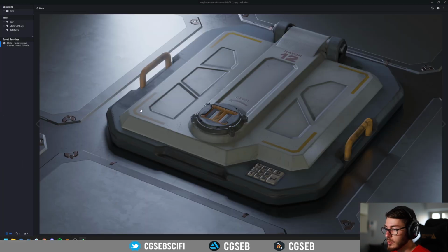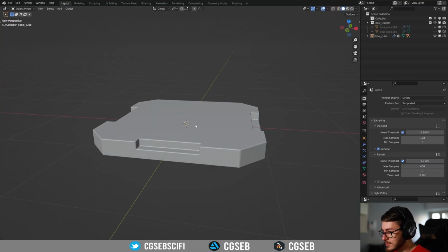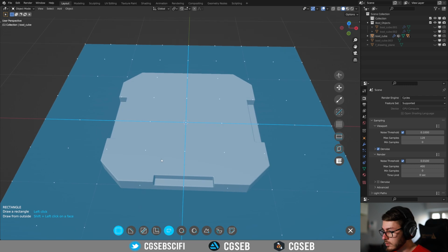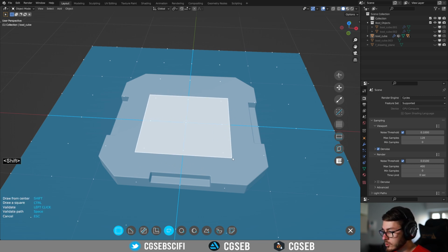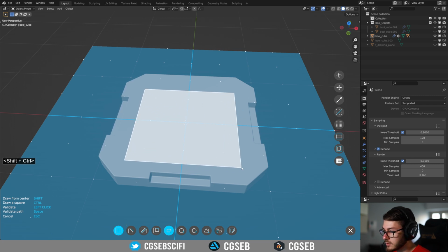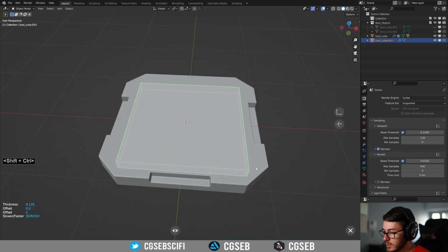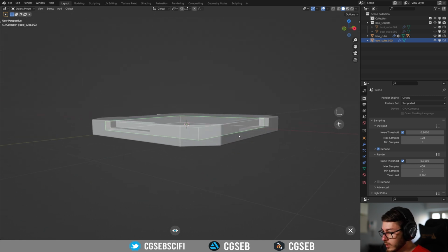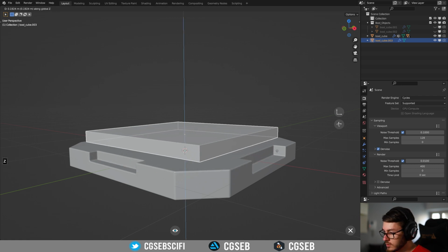So we're going to make a square first, and then we're going to do the rest. So like we did here, creation, show the grid. Make sure you don't select the object when you do a creation because it will create on top of it. Here we can just do this. We can press Ctrl and Shift to draw from the center and keep it square. So I think like that. Then make it something like this. We can press G, Z, and move it up.